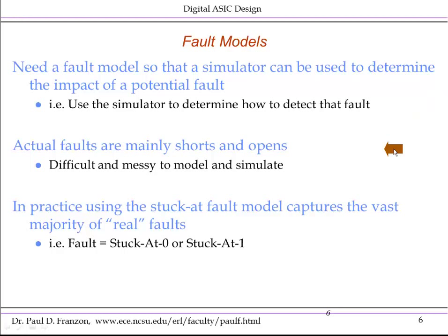This is difficult to apply at the logic level. Let's say you had a net list of your chip, and you wanted to determine what the impact was of a short between neighboring nets. You'd put the short in, and you're trying to work out how to detect that short, and this can be very messy to model and simulate.